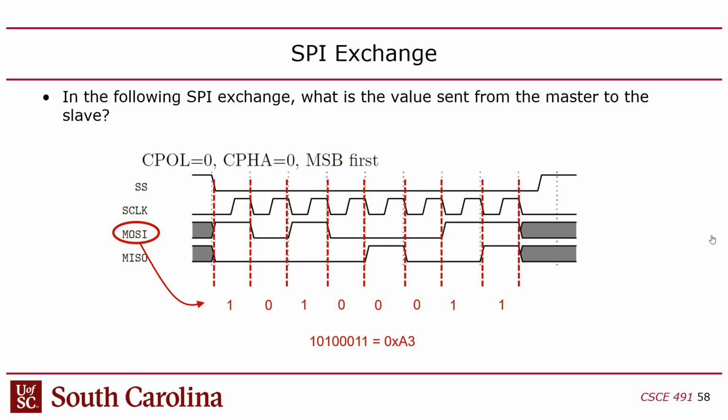So that is when we may differentiate this idea of an exchange. Every 8 bits technically does an exchange, right? But we need to build a transaction level protocol on top of SPI that can be used to perform programmed I/O style access, right? Now remember, programmed I/O, what is that? It's a load or a store, unidirectional.